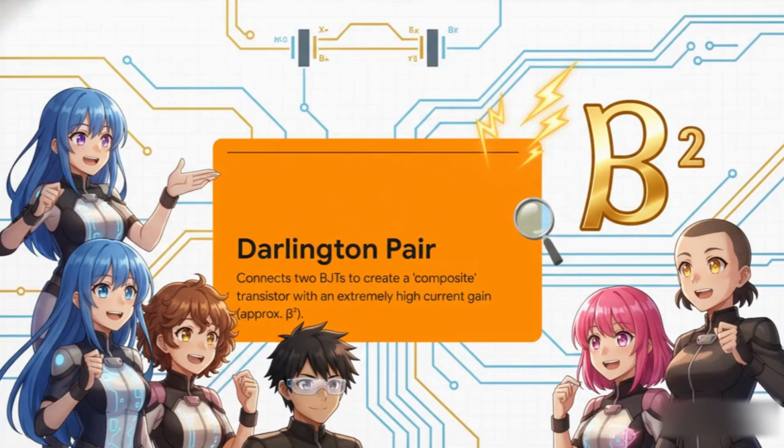And finally, the Darlington pair. This is kind of like cascoding, but it's for current gain instead of voltage gain. You wire two BJTs together so they act like one single super transistor. And its current gain is roughly the two individual gains multiplied together, beta squared. It's just a really simple way to get enormous current amplification.